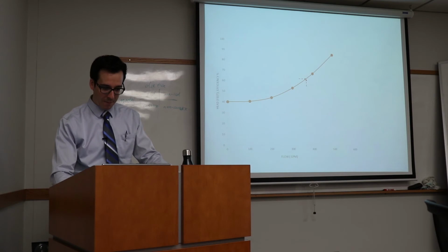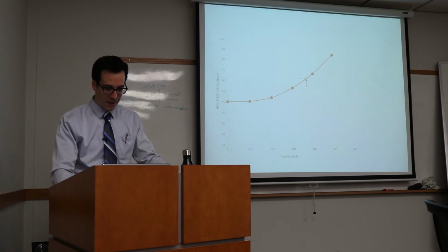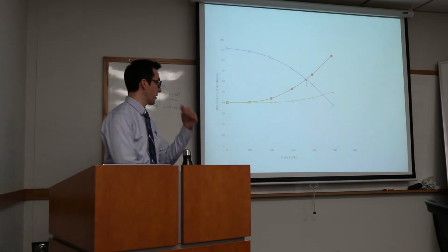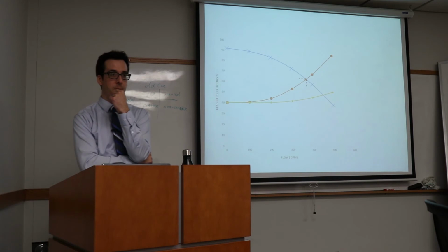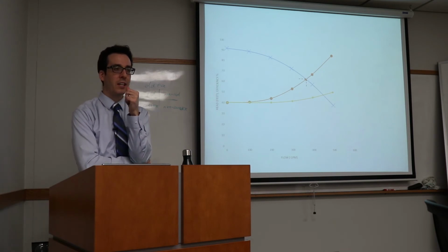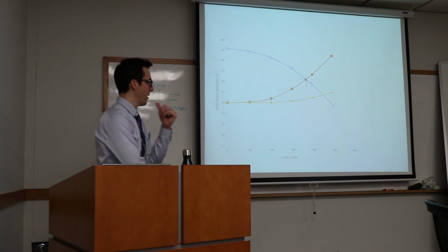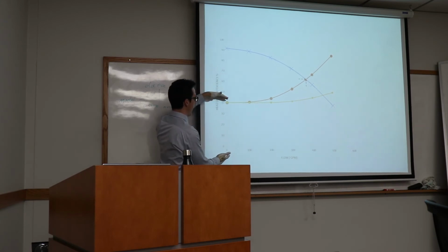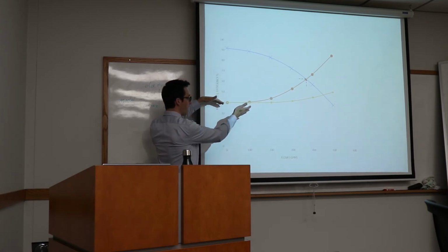So that person came up with the system curve, but what we found is that it's too conservative, right? So we expected it to be there, 370 and 65, and that's where it crossed our pump curve. But in reality, the system curve looks more like this. It's a lot shallower. Okay, there's not as much friction head as we thought. So remember, this part is the static head, and then anything beyond that is the friction head. So this one's actually pretty flat.